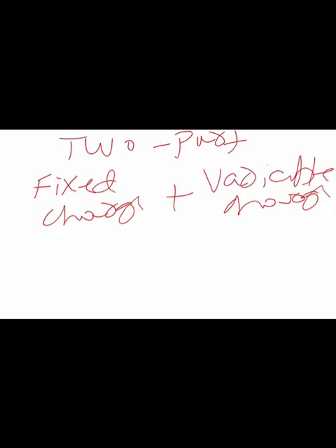Now you could have observed in your energy meter bill, there will be one fixed charge and the sanction load. Depending on that, you will be charged the fixed charges. It is nothing but the maximum amount of power you are going to use at a particular instant. That is the maximum demand or the fixed sanction load we would have taken. So it will be 1 kilowatt, 2 kilowatt, depending on what all the equipment you will be using in your home. You should choose the fixed sanction load while sanctioning the energy meter. So let us consider this one as a 2 kilowatt sanction load.